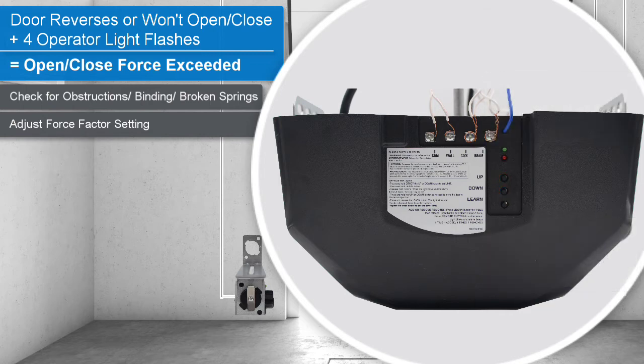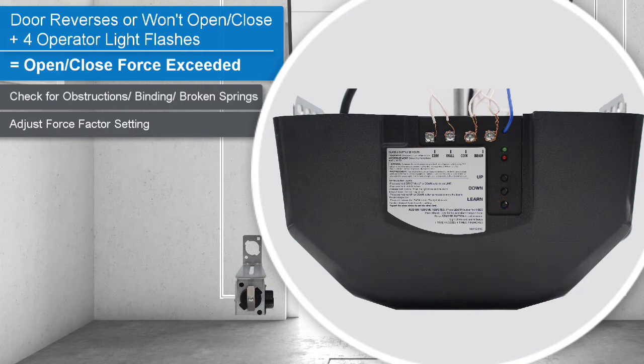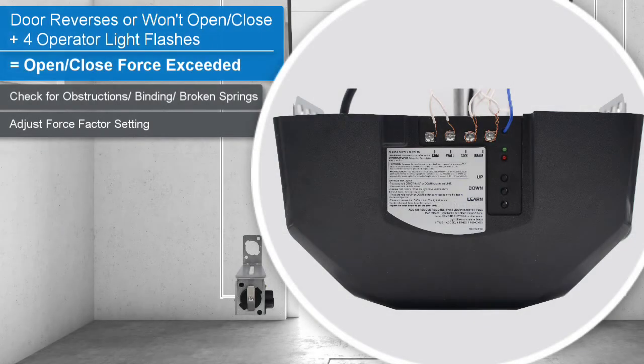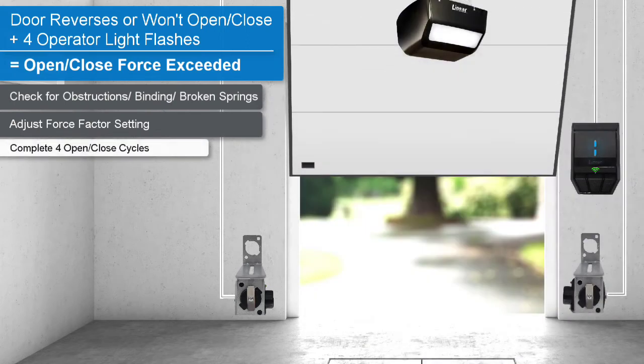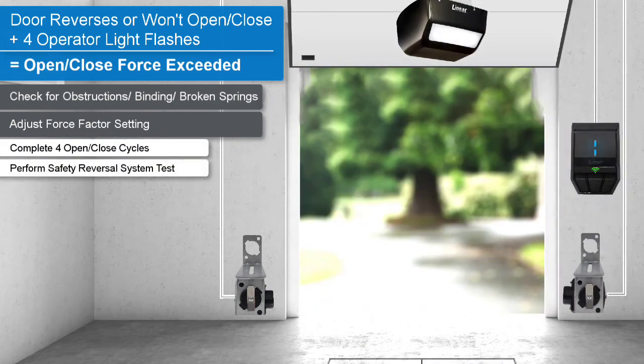Once you're done selecting the new appropriate force factor settings, press the Learn button to store the setting and exit setup. The operator light and red and green indicators will flash 2 times. Note, if you're idle for more than 1 minute, the operator will return to normal operation and its previous force factor setting. After changing the force factor setting, run the operator for 4 complete cycles, and then perform the safety system reversal test.